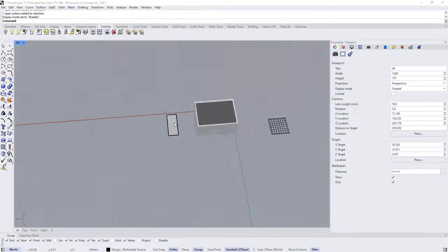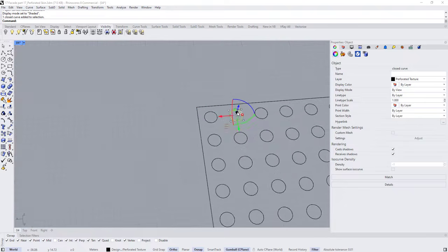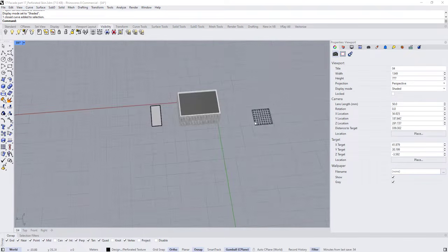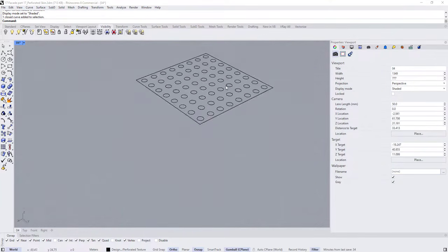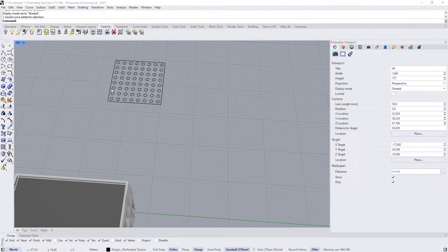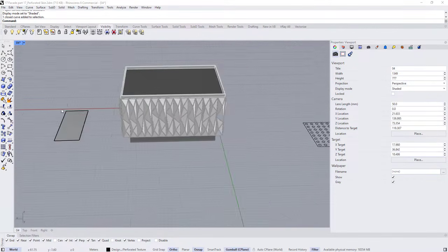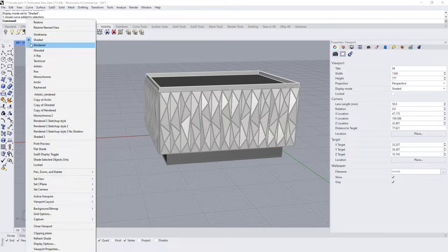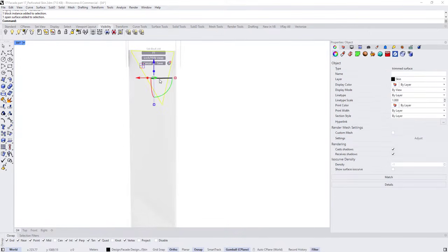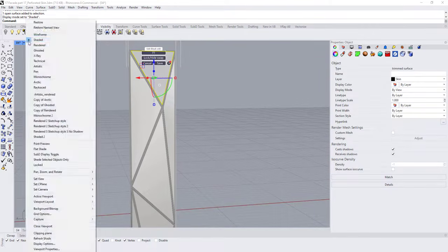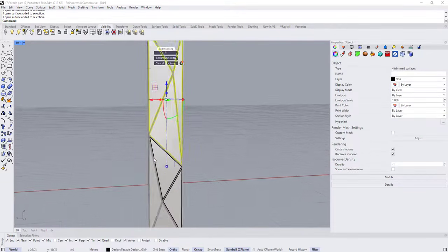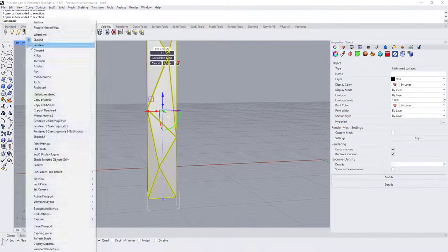And of course, we can repeat this technique using any shape. Instead of circles, you can use triangles, squares, or any type of shape. But just make sure the spacing here is half the spacing in the middle to make sure it's seamless. So yeah, let's apply this texture. Double click here and choose select shift, switch to the shaded view. Select this one, hold shift to select multiple faces at the same time. Switch to the render view.